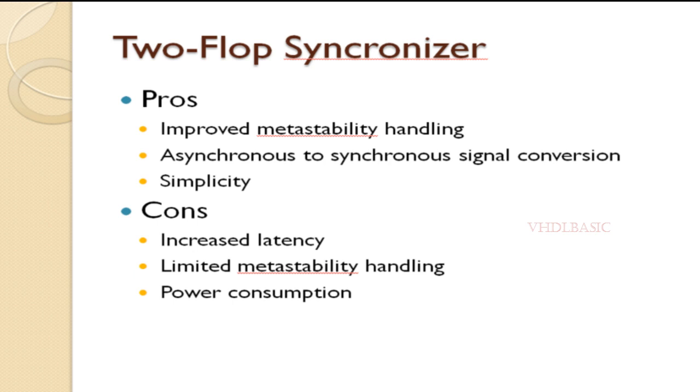Moving to the cons. Increased latency. Due to the double synchronization process, the two flip-flop synchronizer introduces additional latency compared to the single flip-flop synchronizer. The output signal is delayed by two clock cycles, which may impact real-time or latency-sensitive applications.